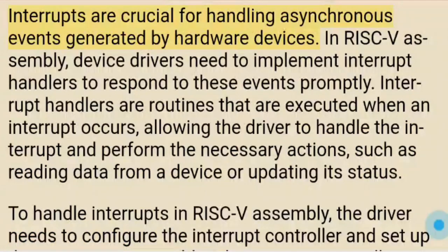Interrupt handling. Interrupts are crucial for handling asynchronous events generated by hardware devices. In RISC-V assembly, device drivers need to implement interrupt handlers to respond to these events promptly. Interrupt handlers are routines that are executed when an interrupt occurs, allowing the driver to handle the interrupt and perform the necessary actions, such as reading data from a device or updating its status.